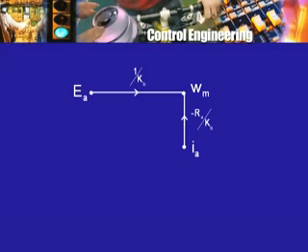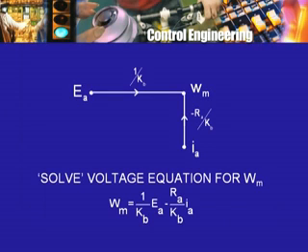omega m is multiplied by KB. So think of transferring that to one side. So KB omega m equal to EA minus IARA. Therefore omega m will be 1 divided by KB into EA. So there is a transmittance from EA of 1 by KB. So I have put an arrow, a line with an arrow, and the transmittance is shown there. And the second term is the minus RAIA divided by KB. So here is the other line going from IA to omega m, and that is minus RAIA divided by KB. Therefore minus RA by KB is the transmittance.